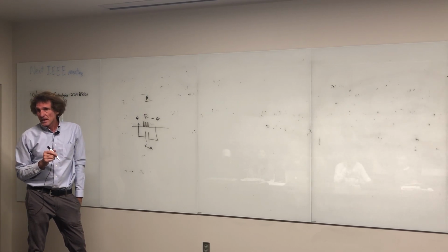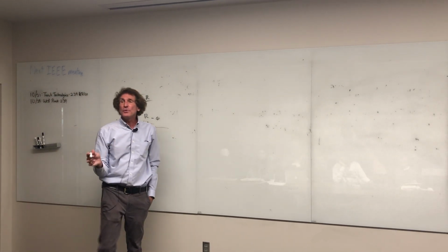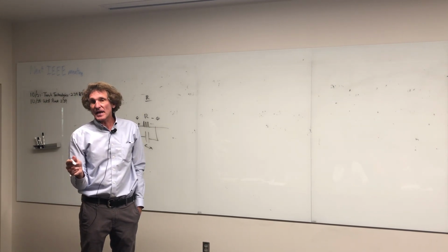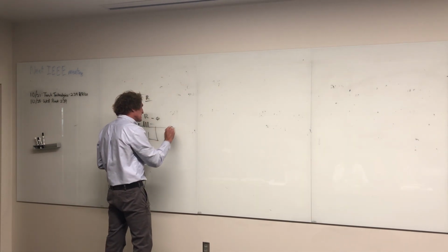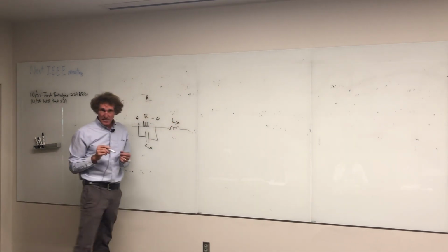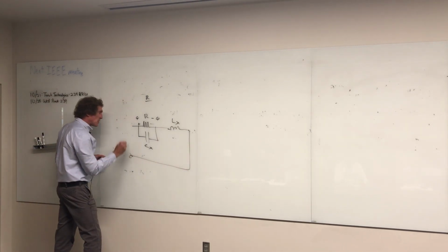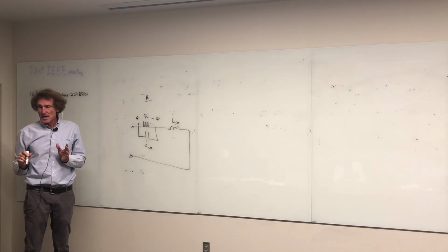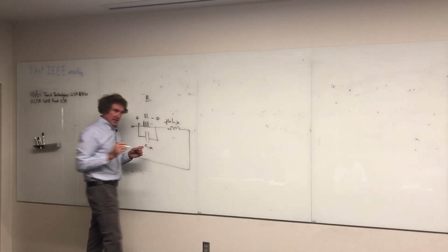Now, the second thing you have in here is wire. No matter what you do, wire creates a magnetic field if current goes through it. And when it does that, it causes itself to have self-inductance and internal inductance. You cannot get around that. So the way we model it is this: we put an LX here, unwanted, but still there. That's a first order model, I do this with EMC, of what a resistor really looks like.